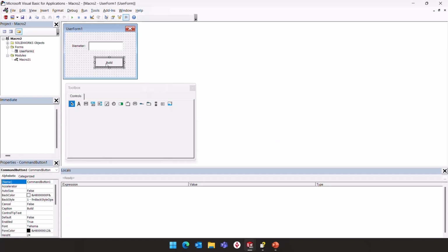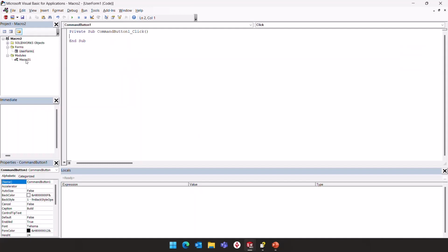Now when we click on this button, we need to actually call that new create cylinder subroutine. So if you press Control J, it'll give you this IntelliSense. Here we see that control create cylinder. Now, if we were to leave it as is, when we click the button, it's just going to create that 5-inch diameter circle, and it's going to extrude it 5 inches.